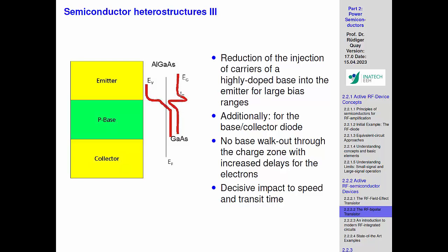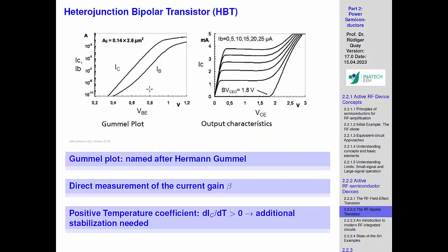So the electrons can still tunnel nicely into the base, as we just explained, also with the support of diffusion, but they cannot so nicely mount this energy barrier into the emitter, which would increase the base current and would kill our current amplification. Yeah? Because this ratio, then you can really show that if you compare devices with such a barrier and without, you can get the same current, but you simply get different levels of leakage.